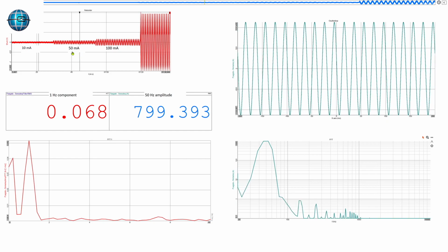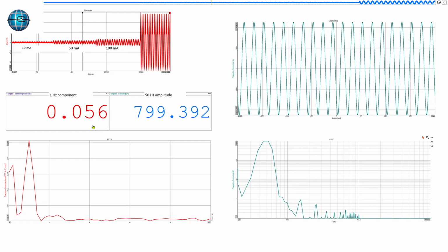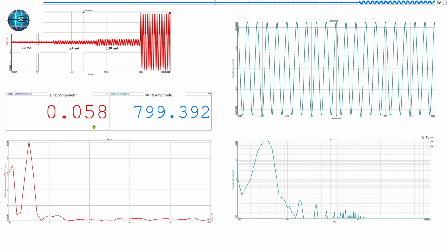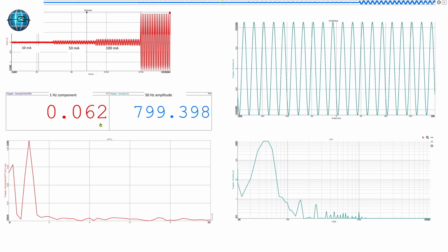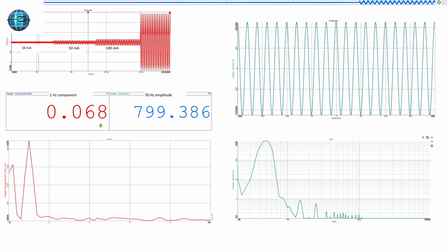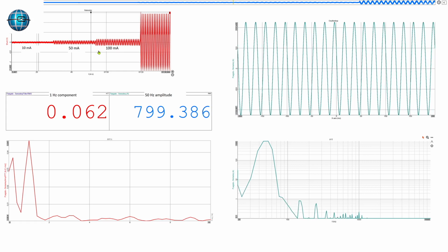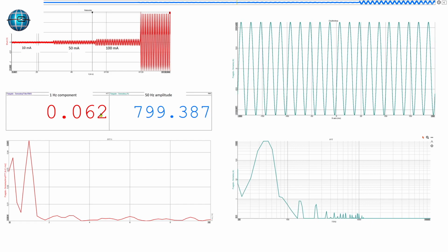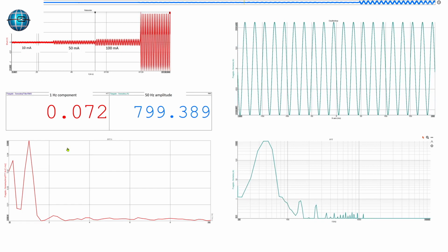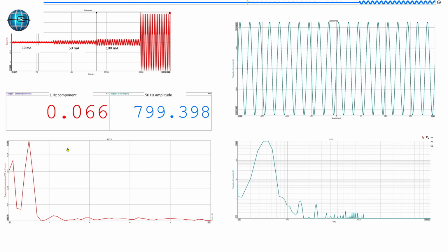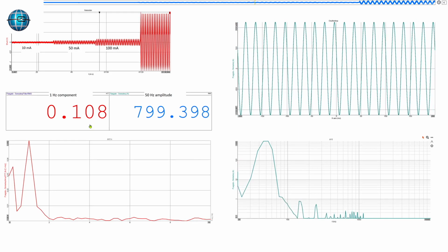But I would say we are here in the 50 milliamp range. We are very stable, and it's still a quite good measurement for the big inner diameter of 400 millimeters. So a lot of electromagnetic fields could couple in. So now we reach the 100 milliamp in a few seconds. Yeah, it takes some time to calculate the right RMS value, but here we are, 100 milliamps.